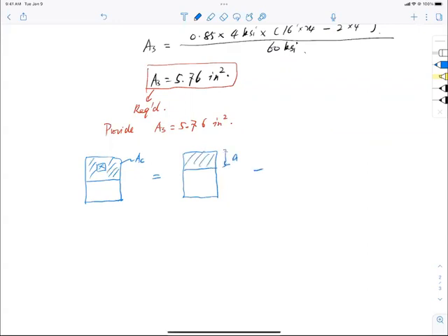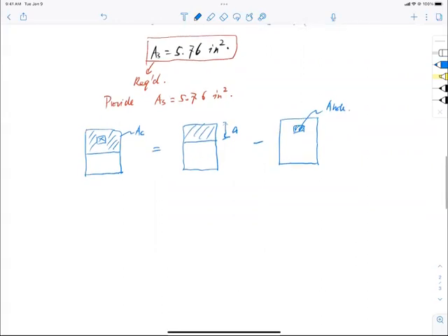Okay, subtract the same section, but with a tiny compressive zone of opening. If I can do that, then I can start writing my equation. So Mn should equal the compression from the total compressive area, plus this, minus this, multiplied by the lever arm, which is JD.